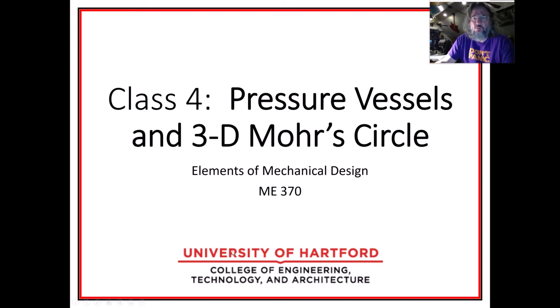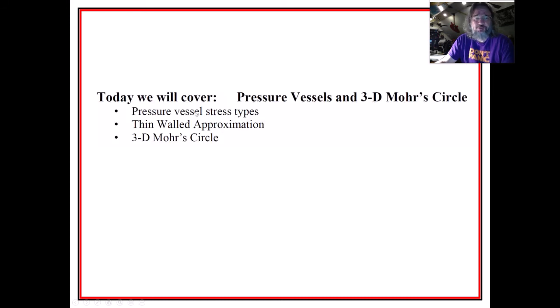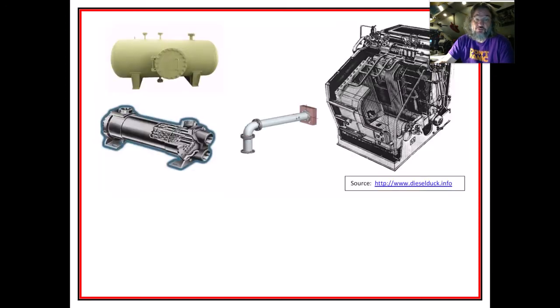Try it out. Anyway, we're going to introduce pressure vessels today, and we're going to take a look at the different pressure vessels. There's different types of stresses in pressure vessels, extra types of stresses we haven't covered in classes 2 and 3, which are the review. Maybe you've had pressure vessels in mechanics of materials, but if not, we're going to introduce them today. One of the main important topics within pressure vessels is that there are easier equations we can use when pressure vessels have thin walls, right? So we call that the thin wall approximation. And then we're going to introduce 3D Mohr's circle as well, and you'll see why that's relevant to the pressure vessels.